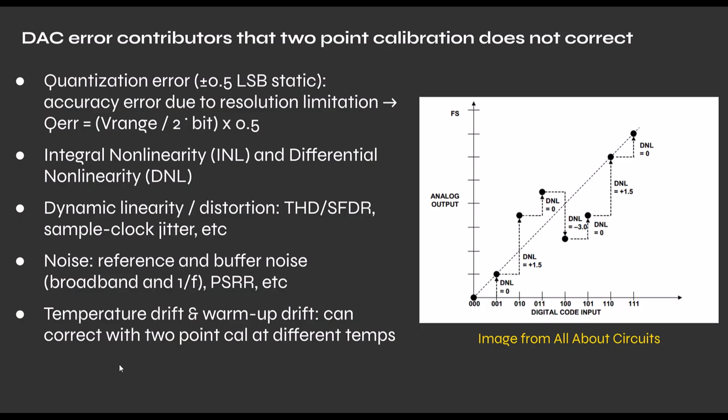For this example, our range is like 8 point some volts and change, and we have a 14-bit DAC. So our quantization error is about 250 microvolts. If you remember, that reading we had was about 200 microvolts. Now, 250 microvolts, of course, is the max quantization error. So you can see that the error that we still saw in the DAC's output was probably mainly quantization error.